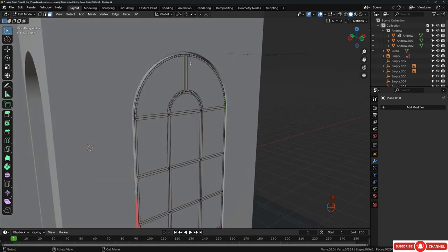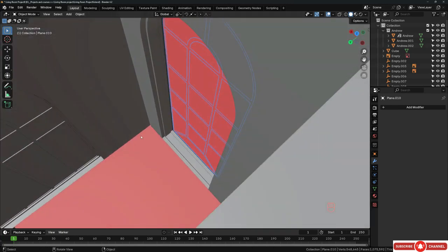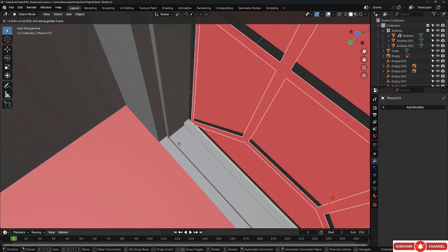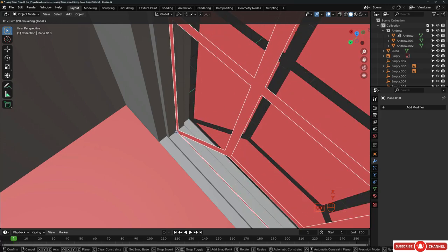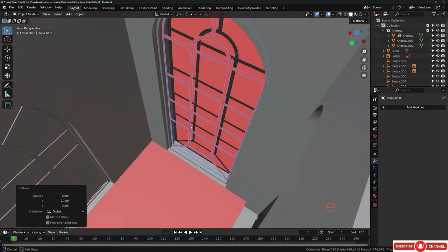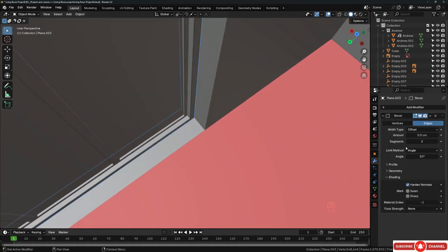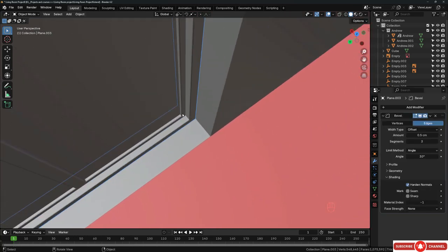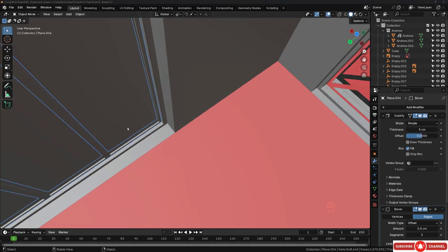And just hit P and then S to separate this out, and that's it. And now I will select this frame and use it. Hit G to move this to the Y-axis. Hold Control to snap it here to the middle. That's very cool. And we gave it, all right, the thickness was 4.7. All right, why don't we give it 5? I guess that will be better.